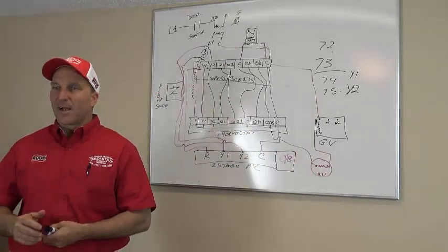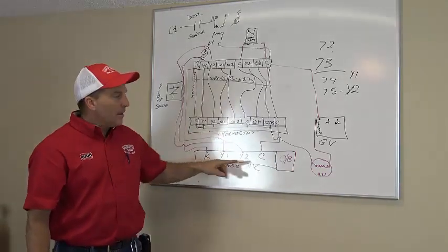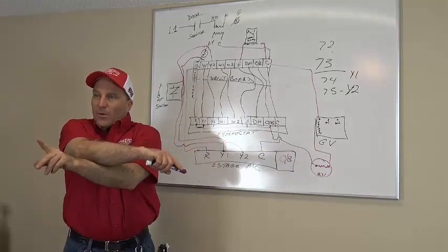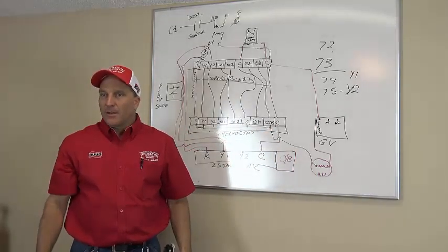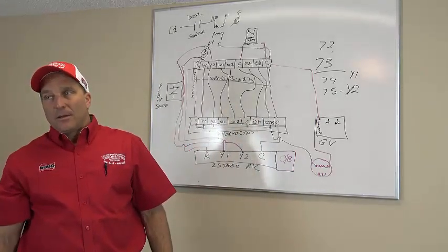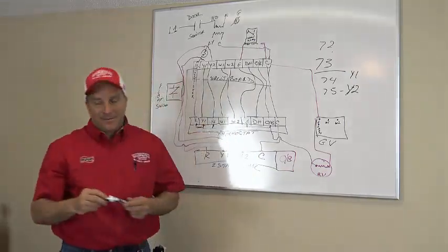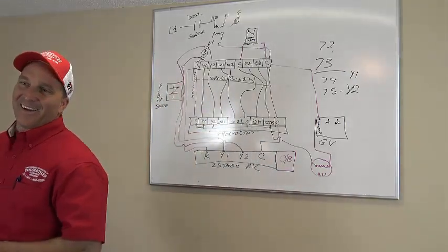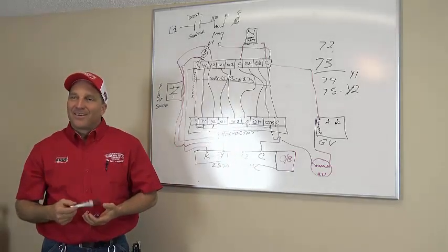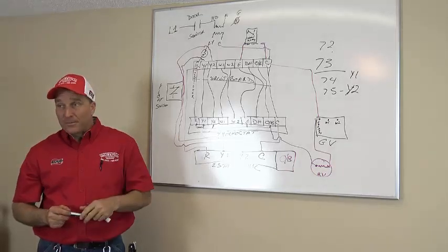Let's think about this, guys. My air condition comes on Y1. So it could. My reversing valve energizes, so it reverses my refrigerant flow, right? Okay? What's my second stage of heat? It's the gas valve. No, my second stage of heat is not that, it's the Y2. Because it's all running off the outside unit now. Right. And the heat pump, because it's running backwards, basically. I'm running the heat pump.